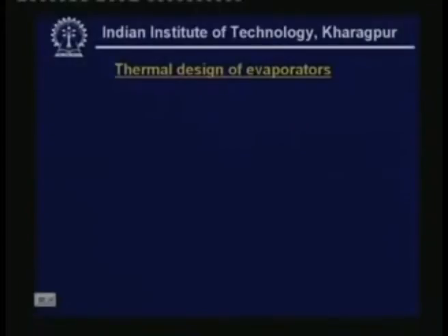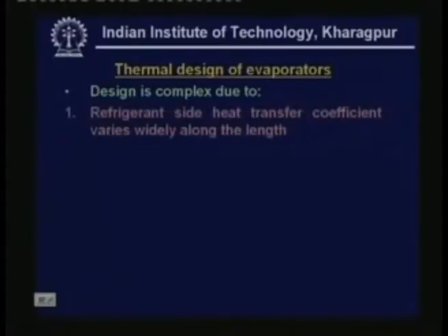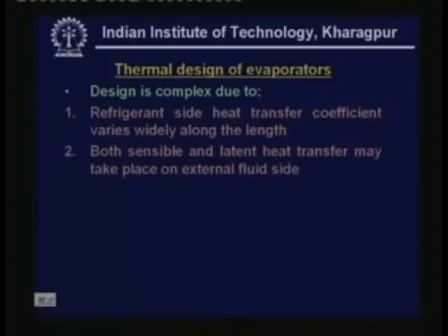I will simply explain the basic principles and the complexities to be considered while designing the evaporator. First, let us look at the complexities. The design is complex because the refrigerant side heat transfer coefficient varies widely along the length. Both sensible and latent heat transfer may take place on the external fluid side, as I have already told. Then there is the presence of lubricating oil in the evaporator.